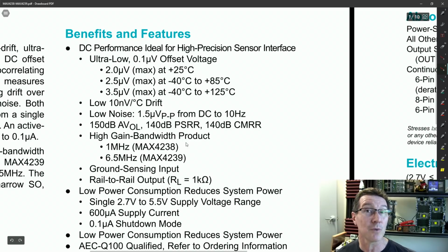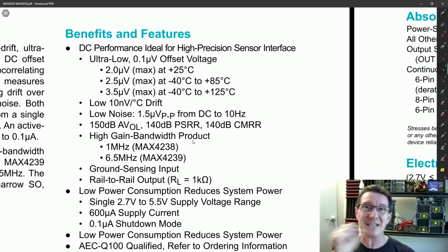You might even want to, this is where you can come a gutser, by the way, when you're designing a product, you rigidly set your specifications. I must have this. And that's it. I draw the line right there, and I must have this bandwidth and this offset voltage. If you aren't willing to negotiate in there, then you either might not be able to find a chip, or you might be pushed into a really expensive solution that prices your product out of the market, for example, or all sorts of things can do that.